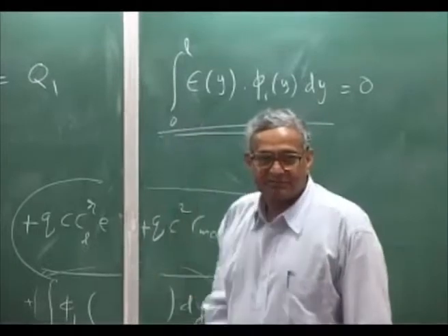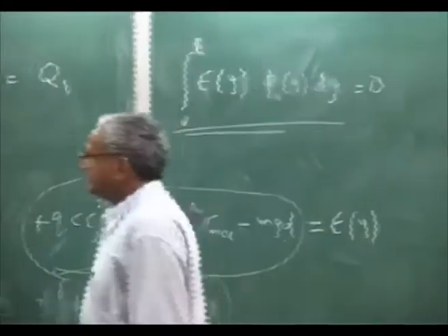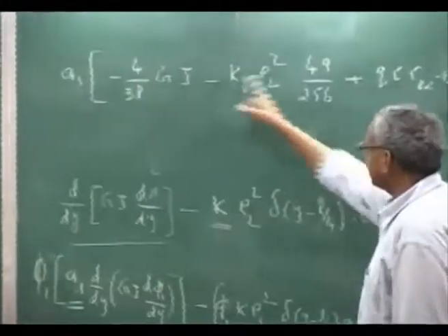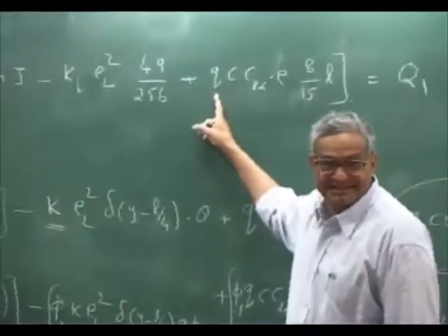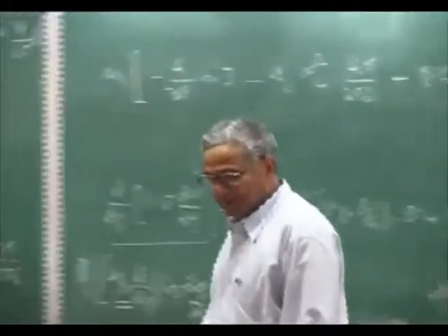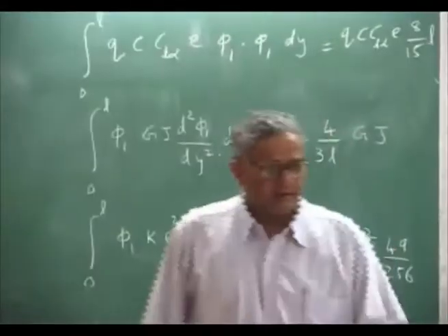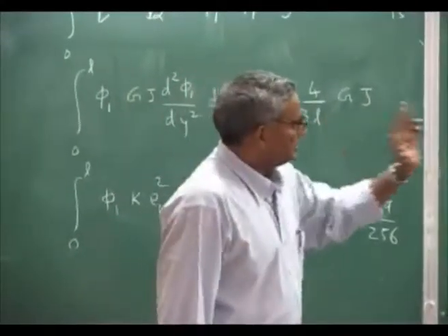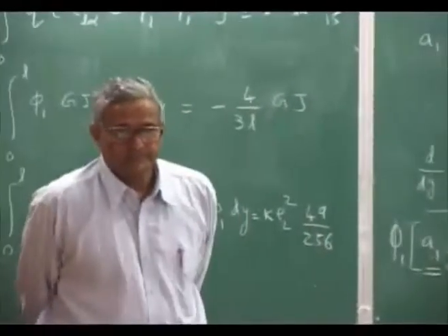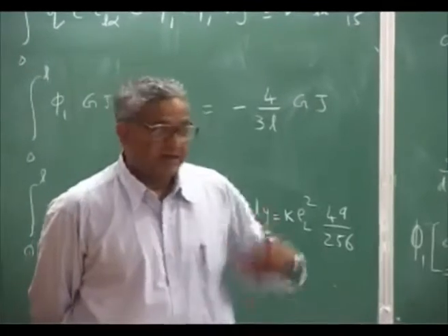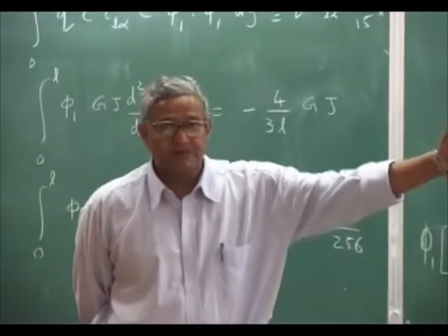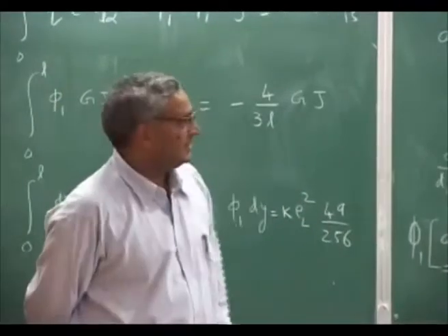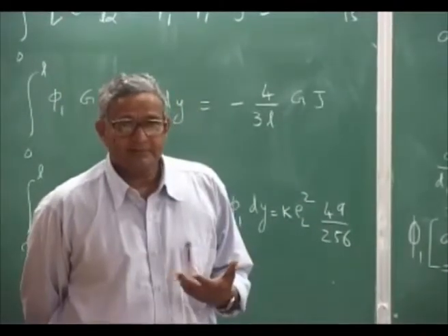So, you may say, what are my unknowns here? My unknowns are A1, of course the rest of the quantity is Q. Now you see the problem becomes like this. If I am given the Q, that means I know the speed of the aircraft, that means I know the dynamic pressure, then what is my deflection?